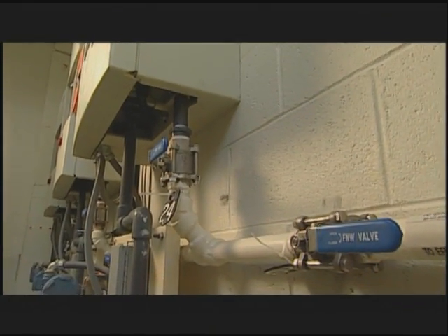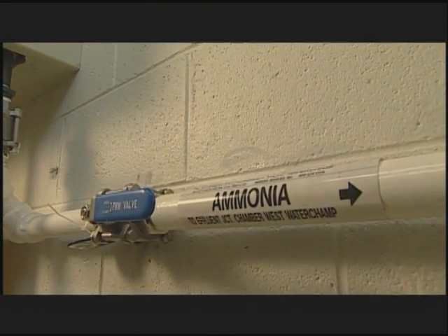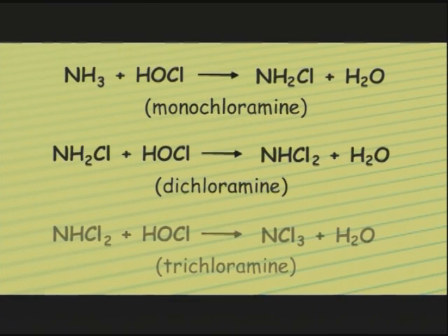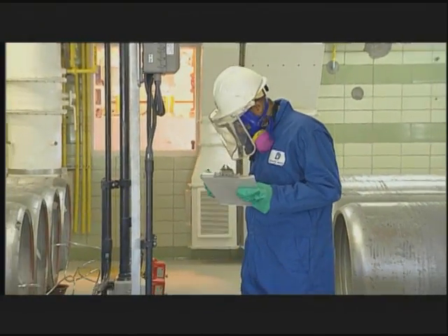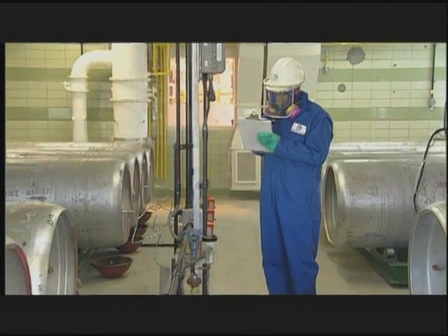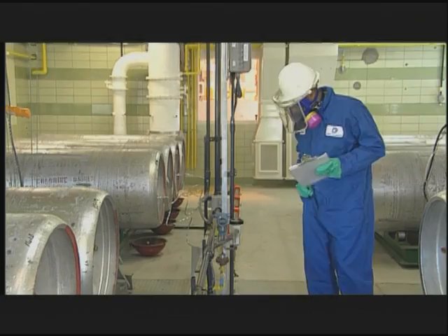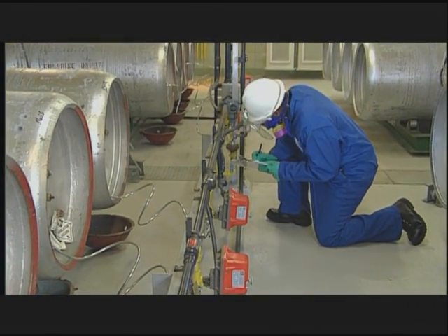One of the most common reactions of chlorine in raw water involves ammonia. In the presence of ammonia, monochloramine, dichloramine, and trichloramine are formed. These chloramines are called combined available chlorine. Chlorination practices frequently provide for formation of combined available chlorine, which, although a weaker disinfectant than free available chlorine, is more readily retained as disinfection throughout the water distribution system.